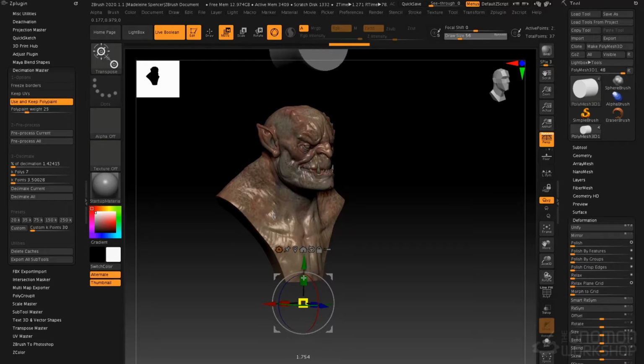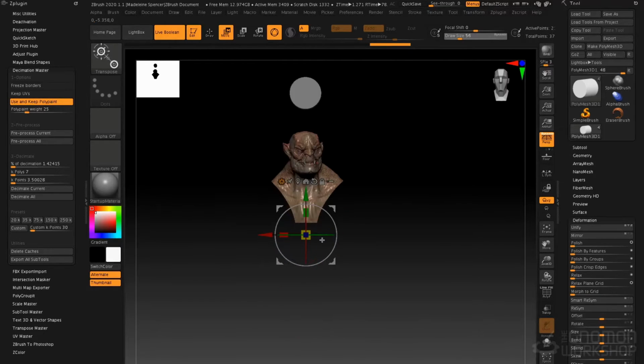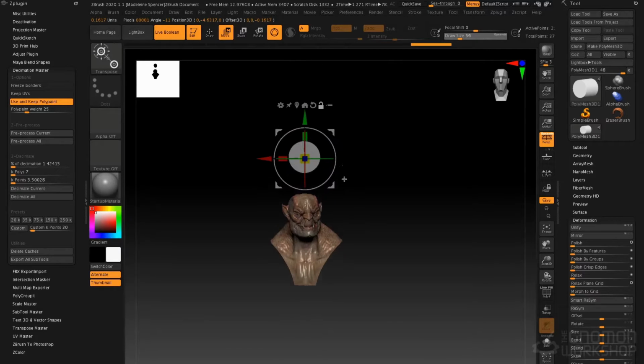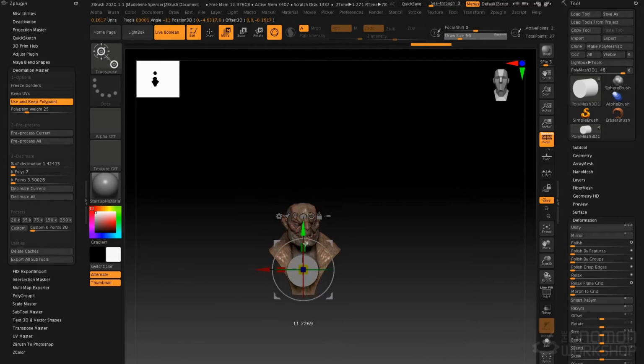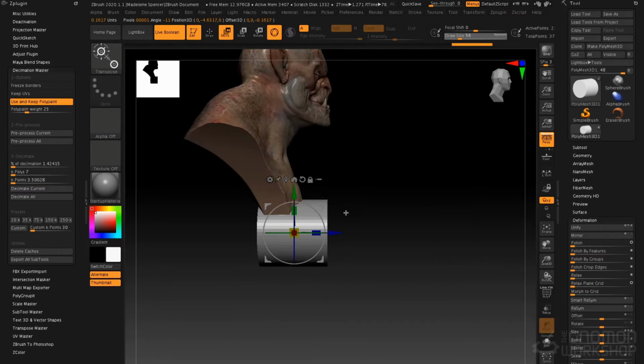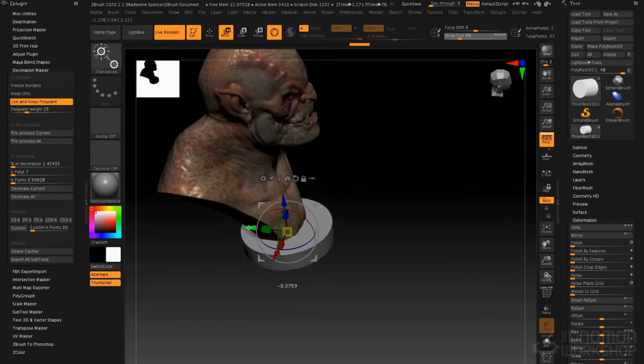There he is, right up there. That's the problem. My pivot is down here, but the object is up there. So let's unlock it, go to the Unmask Center, lock it again, and then bring it down. There we go. Thought something was amiss. Hold down the Shift key and I'll snap rotate that 90 degrees, scale it down, and then scale it up a little bit so we have a nice little base here.